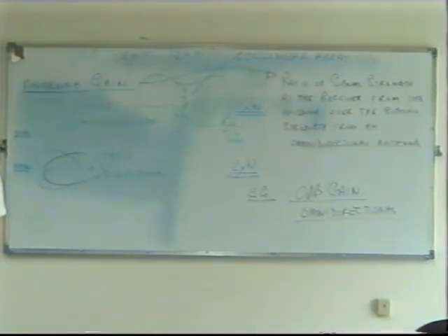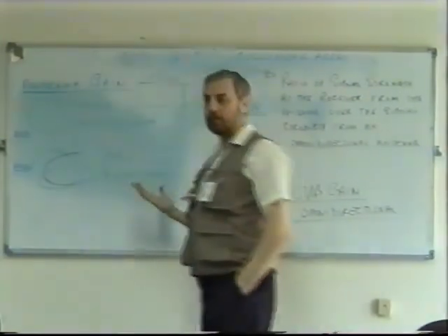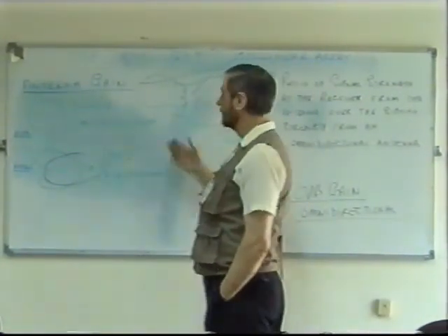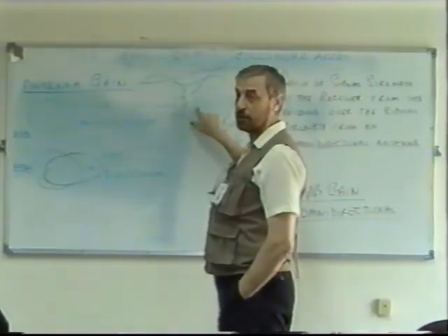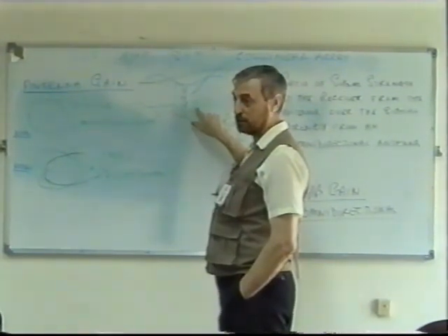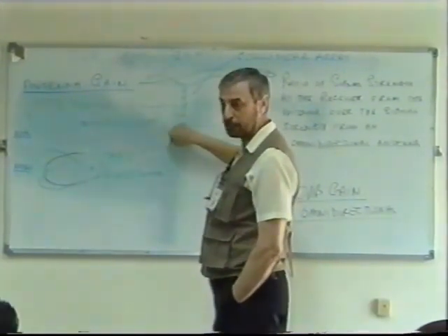When we increase the dB, that means it is more direct. It makes more efficient use of power, and you get a greater signal strength at the receiver. Between 6 dB, yes, it depends on the type of antenna you're using. If it's a stacked array, the reason it's more than 0, like 6 dB, is because it's not wasting power up and down.